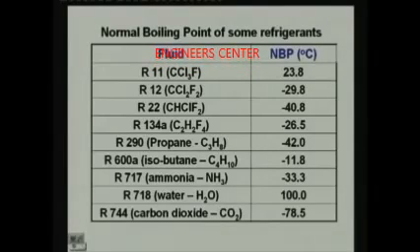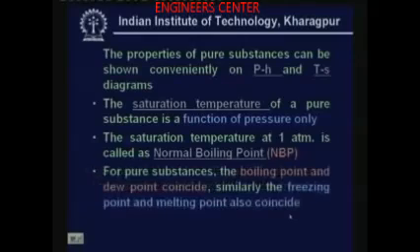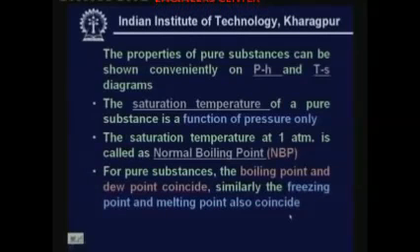Similarly, R22 has a normal boiling point of minus 40.8. R134a has a normal boiling point of minus 26.5. Likewise, you can find the normal boiling points of various refrigerants, and this data is very much available in literature. Now, for pure substances, this is one peculiarity: the boiling point and dew